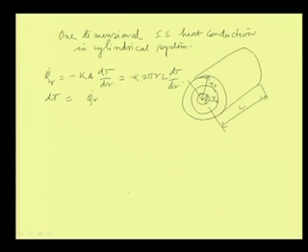Then minus dT is equal to Q dot by twice pi k L into dr by r. Now, if we do the integration, from T I to T O, minus dT is equal to Q dot R by twice pi k L. Again here k is independent of the coordinates, and Q dot R is constant because it is the steady heat conduction situation.